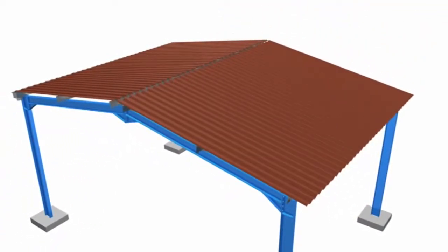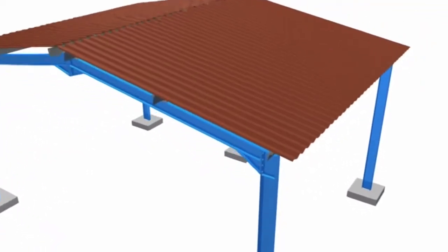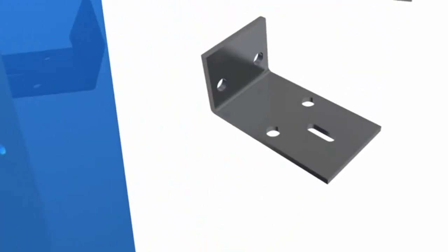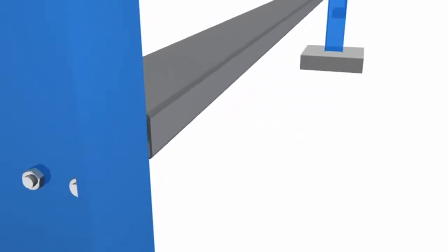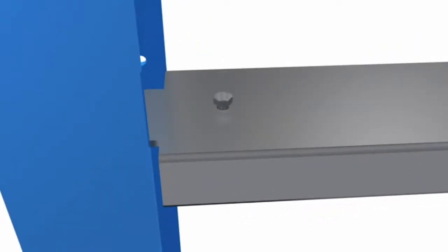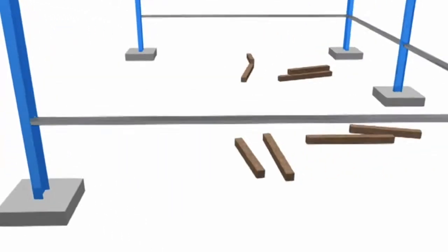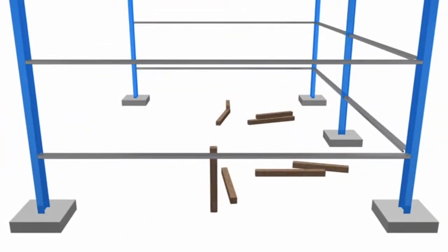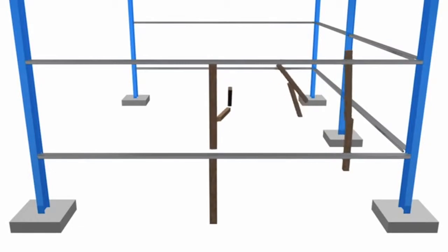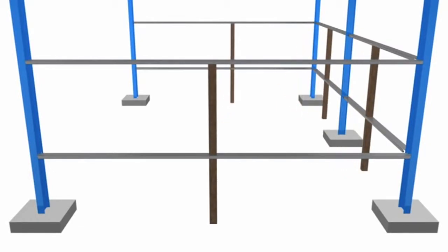Total wind load pressure equals 2.088 times 6, which equals 12.528 kilonewtons per metre. The total wind load for suction equals negative 1.7864 times 6, equals negative 10.7184 kilonewtons per metre. Determining the load combination will allow us to determine what the N and M maximum values were.